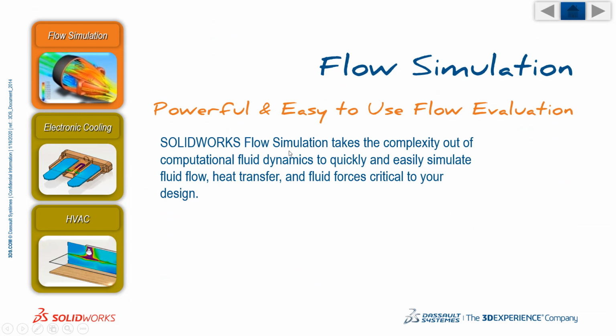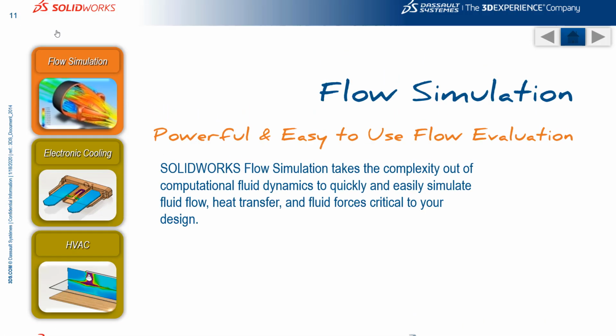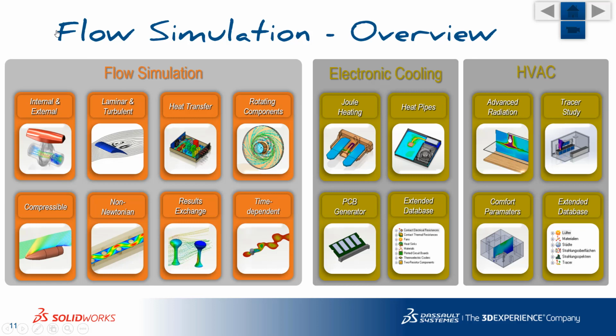Flow simulation is a lot easier to talk about because it basically has one general tool, flow simulation, to capture all things for fluid flow, fluid dynamics, a much more accurate heat transfer than what's in Simulation Professional, a much more robust heat transfer tool. And then you can also add on certain layers like electronics cooling or HVAC. So let's take a look at this. So here's what it looks like.